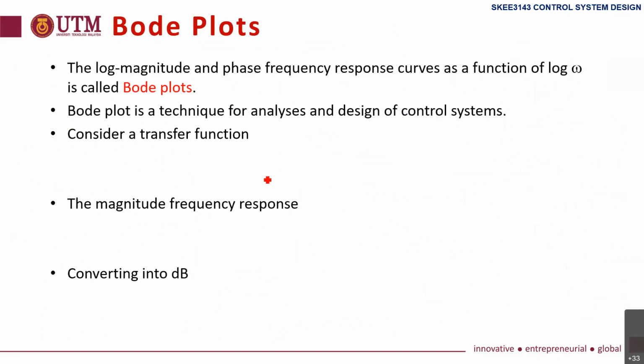Let's go into more detail on Bode plot. The log magnitude in dB and the phase frequency response curve as a function of log omega is called the Bode plot. So a separate magnitude versus log omega, and also phase versus log omega. It's called the Bode plot.